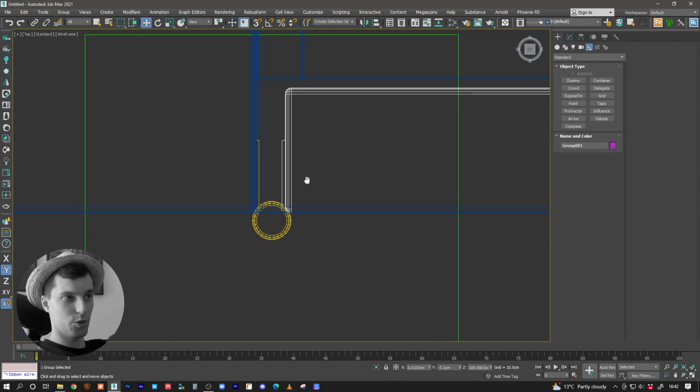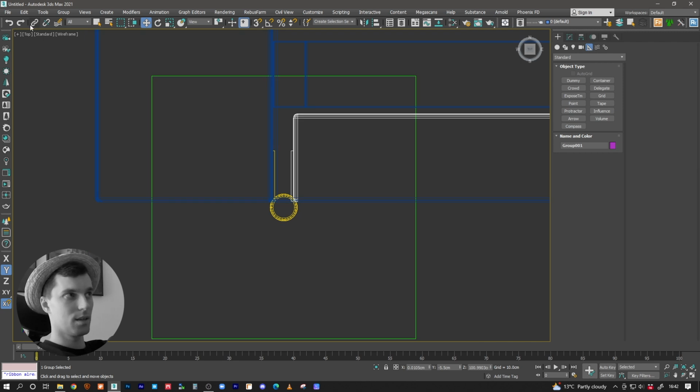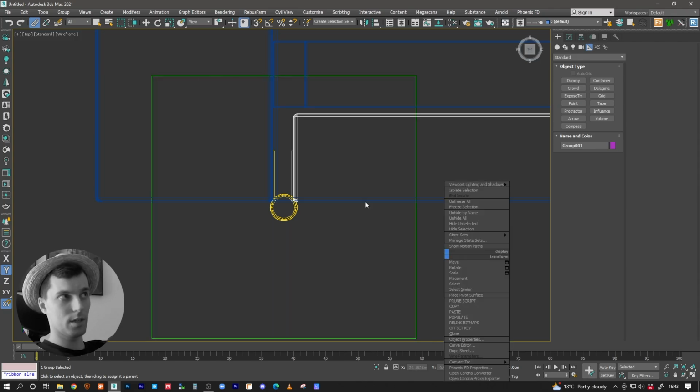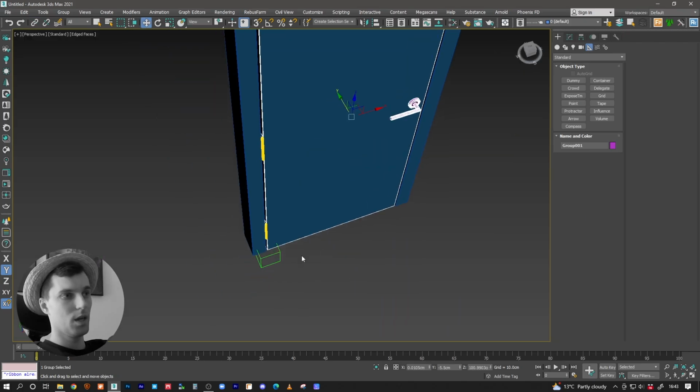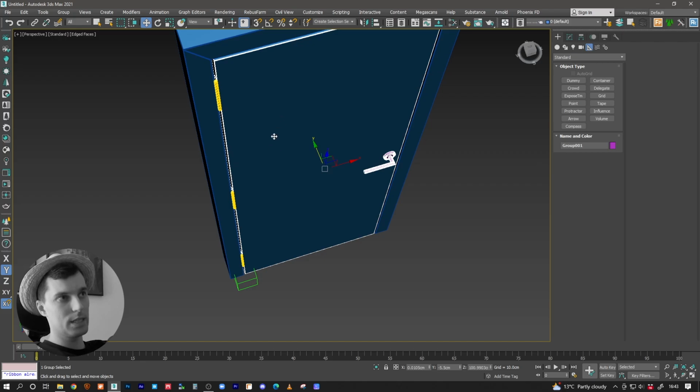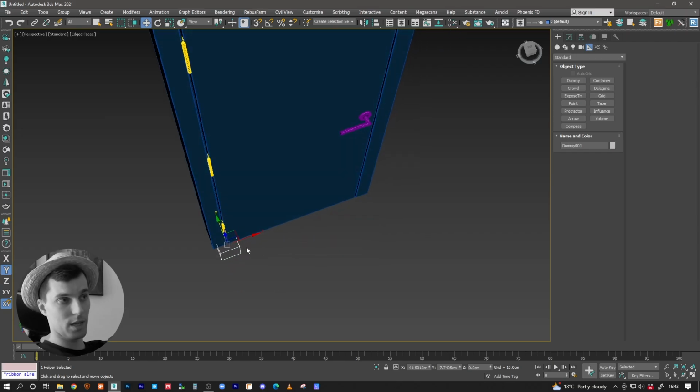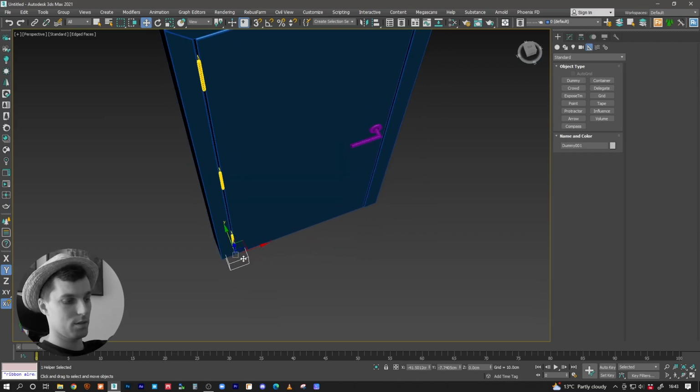The next thing you want to do is select the link tool, right? And drag from the door, drag to, when that white arrow icon appears, bam, release it, right? And then select the move tool, go to perspective mode. So what happened now? Basically what you did is you linked the door that's gonna move to the dummy, right? So I'm gonna select the dummy now because this is gonna be the mother point, so to say.